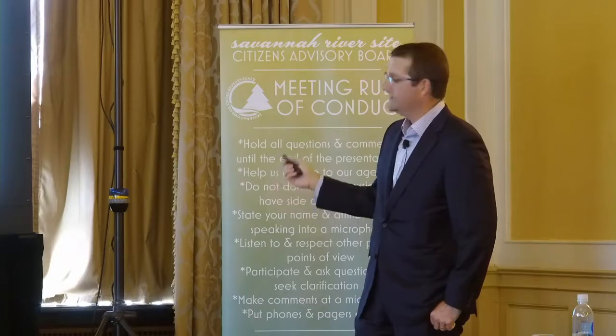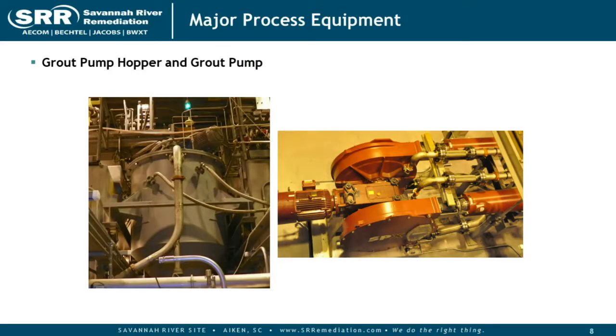All right. Downstream of the grout pump, we have, again, a small amount of process instrumentation. We can monitor pressure, we can monitor flow, we can monitor density, but after that, it exits the process room and then goes through a series of 3-way valves to direct it to whichever is the active disposal location at that time.